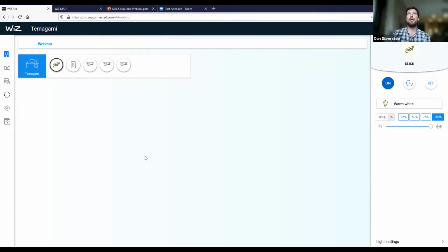The downside is that it's actually more expensive than adding an individual room controller. I'm not going to get into specific pricing, but our EDC driver is a premium piece of electronics that carries a cost factor with it. By moving to the distributed model, where you've got one driver and individual segments of track, so we're putting the OnCloud controller in the actual track, you only have one driver for multiple segments. You get more flexibility, and it lowers the overall cost of installation because the OnCloud controller itself is priced less than an individual driver per segment.